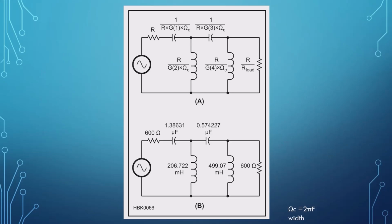But like Roger said, it depends on what you're trying to match the filter to, because filters are used in more than just RF output. If you think about it, filters are used on your input side. Also during your mixing, you'll have an intermediate filter there. Normally they'll use a crystal filter to filter your intermediate frequency before you do your final mixing, to make it as clean as possible.